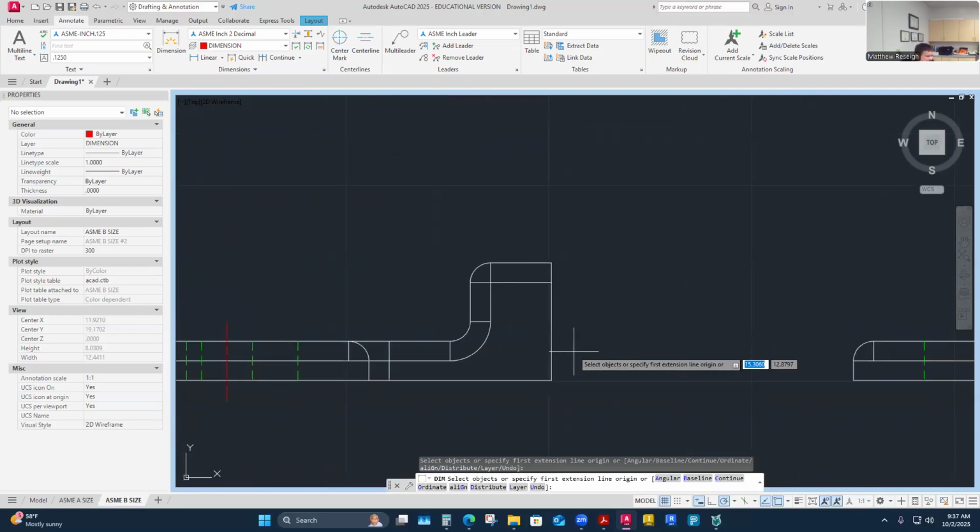So I just want you to think of the way you're pulling dimensions, where your intent lies and where that dimension starts and stops. Because a dimension has a start and stop. It has arrows, and it's misleading when you look at a dimension because you're thinking, well, it goes in both directions. No, think of dimensions as coming from one point to another point. So there is a start and finish line, and think of your dimensions like that.